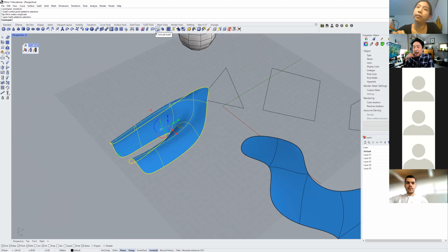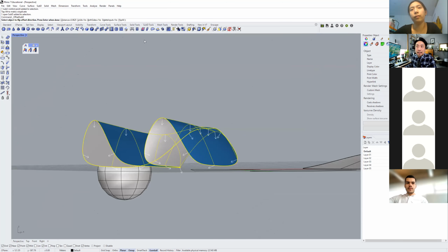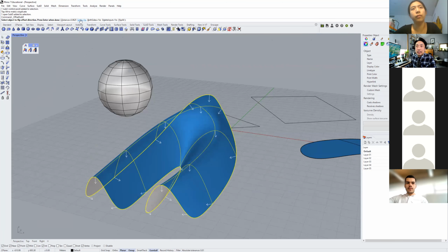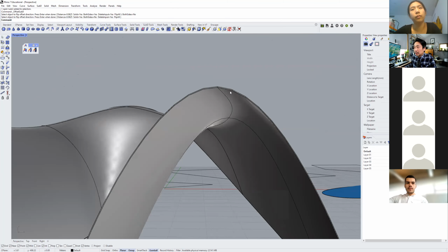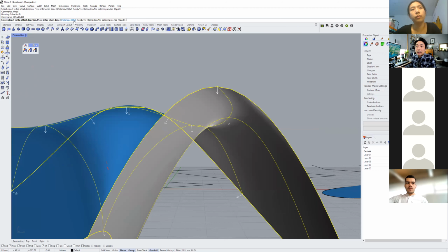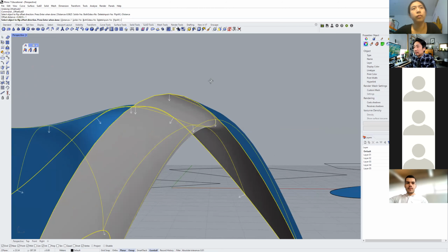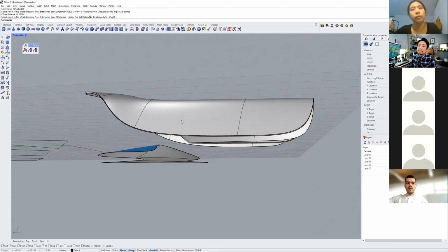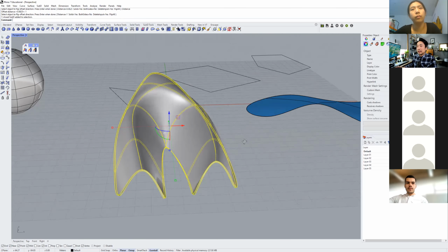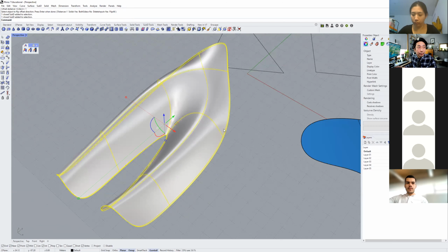Now, if I'm rendering, and this is, let's say, a roof, I want to create an offset and give it thickness. So it's as simple as just coming here and clicking offset sub-D, give it a distance, say it's a solid, don't offset both sides, just offset one side. Oh, it's way too thin. So let's do it one more time. Distance would be, let's say 1. Okay. So it's a perfectly offset object. And it's now ready to render and 3D print it.